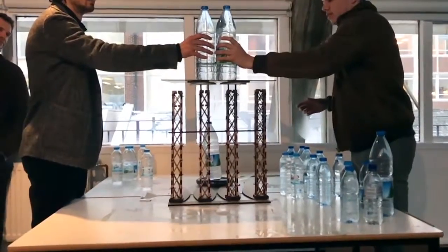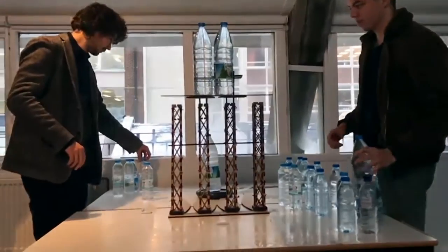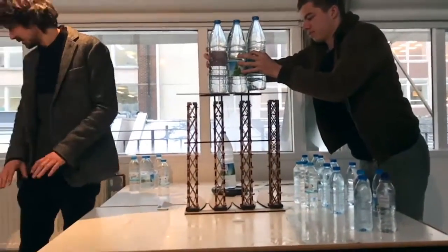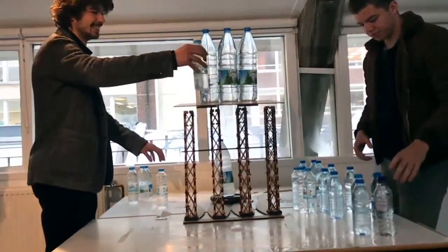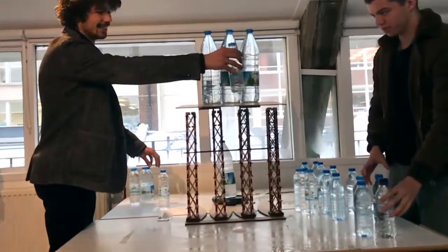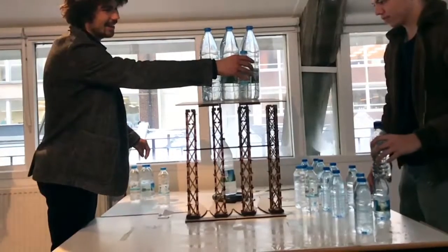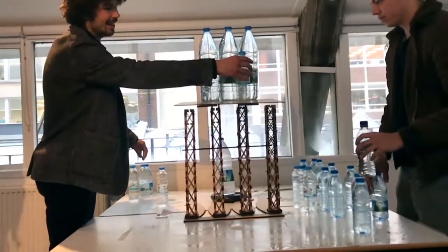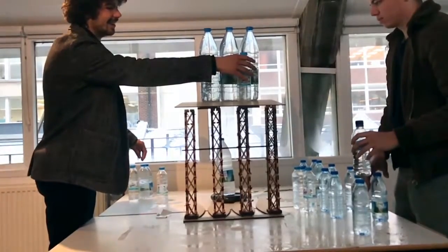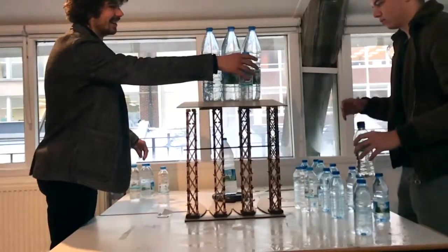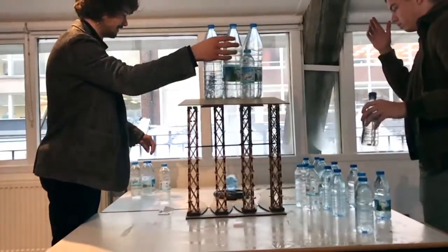Mechanism. If we now look at how our structure failed and where it failed, we have to keep our eyes on the back, where we can see the weight and a water bottle on top of it. And we have to look also at the connection between the truss and the main platform. Now, as Davide adds the last 500 grams with a half liter of water, we're going to notice how in the back, the string, which is under the counterweight, is going to go in strong tension, putting the counterweight in balance, lifting it a little, and we're going to see the big liter of water fall over.